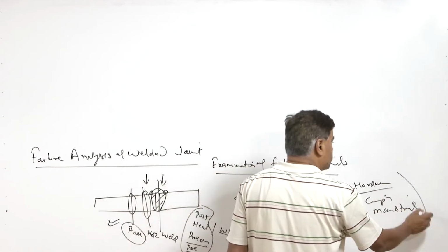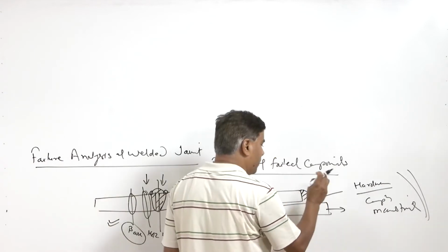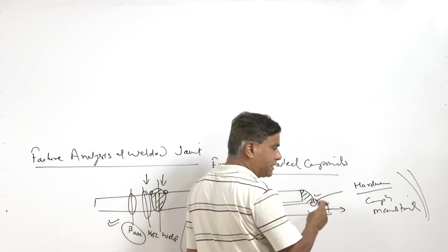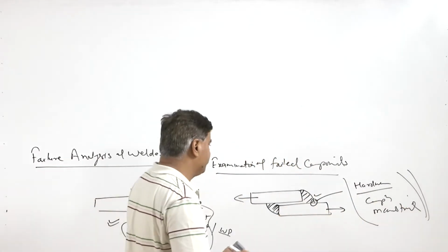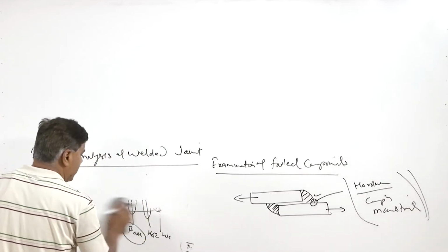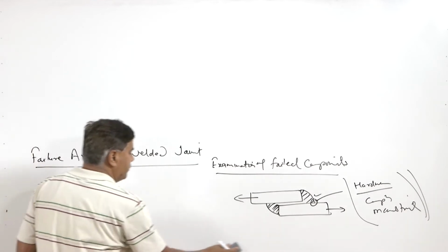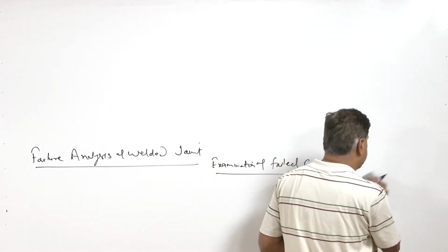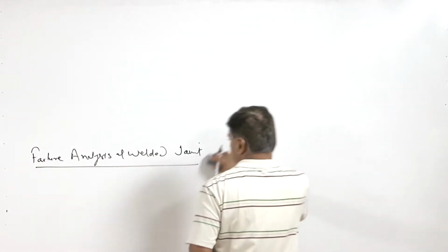So, other factors should also support favorable conditions for nucleation and growth of a crack from a particular location. High stress concentration may be the triggering point, but other properties will also be supporting the same aspect, because of which the crack is nucleating from the particular location. These are the general aspects; even a simple visual examination of the failed component will indicate the kind of things that should be looked into from the failure analysis point of view.